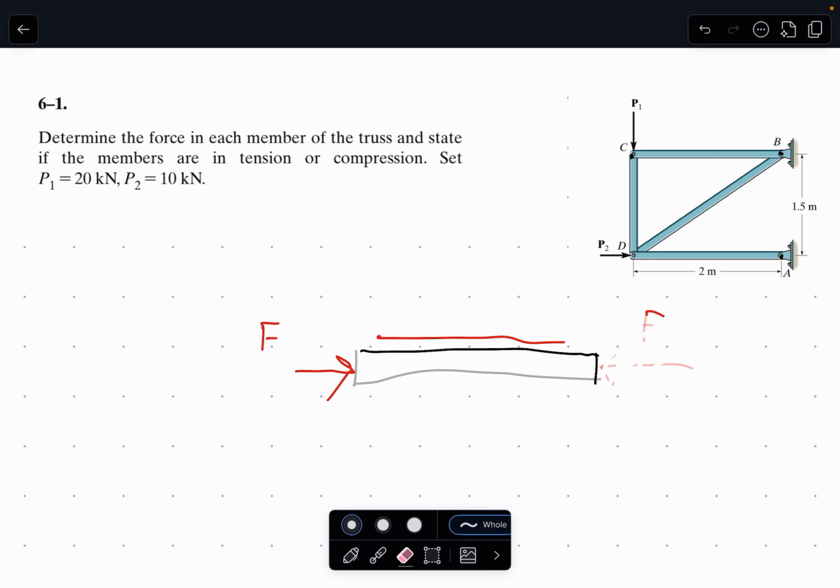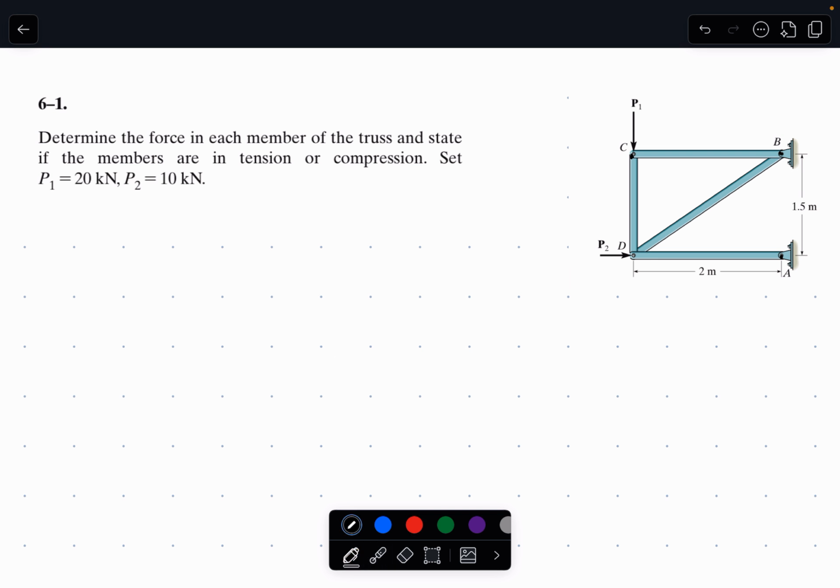Okay? And this is a big distinction between beams and rods. Rod is kind of a general term. Trusses are made up of axial force members, which are only in tension or compression, whereas a beam can have a bunch of shear forces. Generally, the most significant forces on a beam are acting in the shear direction, while truss axial force members act in tension or compression. So we know that these members won't have any shear forces acting on them. It's simply going to be tension or compression.